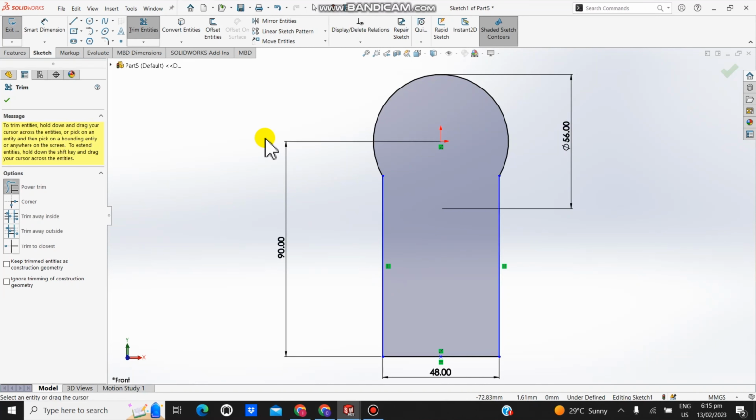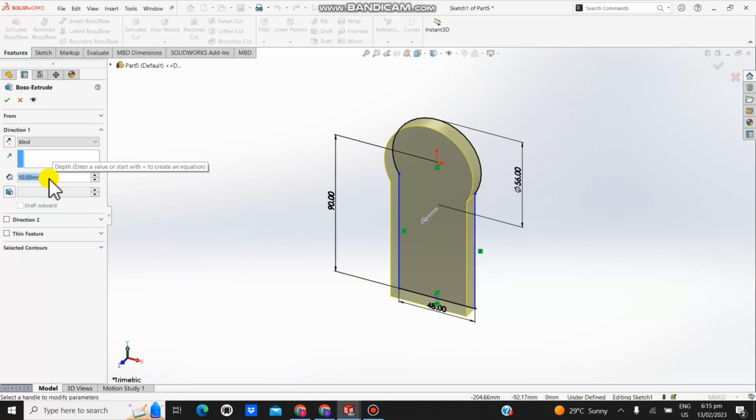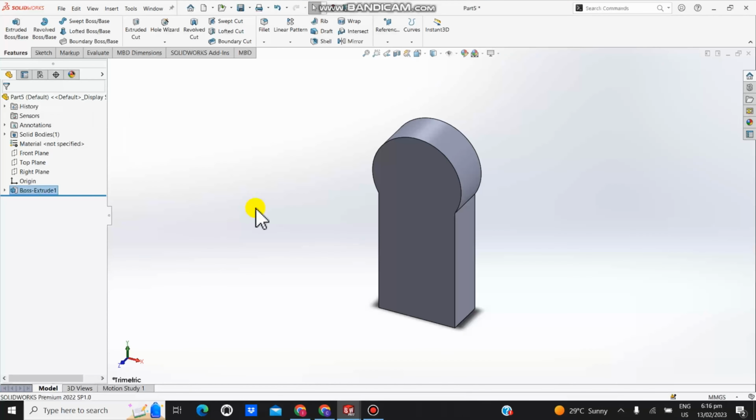The next thing I can do here is to extrude it. When you look at the extrusion, the circular part went up by 55 and the rectangular part was extruded by 24. So we can extrude all of them by 24, and later we add to the circular part to make it up to 55. Because my sketch is enclosed and highlighted, it's ready for 3D modeling. I go to features, click on extrude base, then enter my dimension, which is 24. I type 24 on the keyboard and press enter. I'm done with the first part.